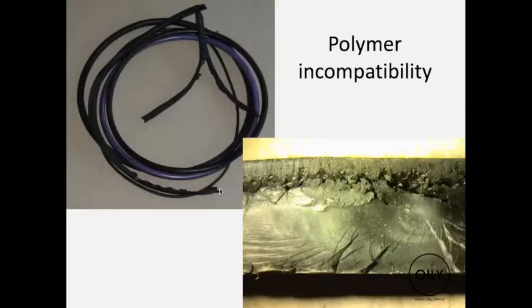Okay, these are O-rings. Inside the engine, you've got the combustion chamber with a sleeve that the piston's running up and down in. Around the outside, you've got big O-rings that seal there. These are breaking up. Again, using the wrong antifreeze in the engine that's not compatible.